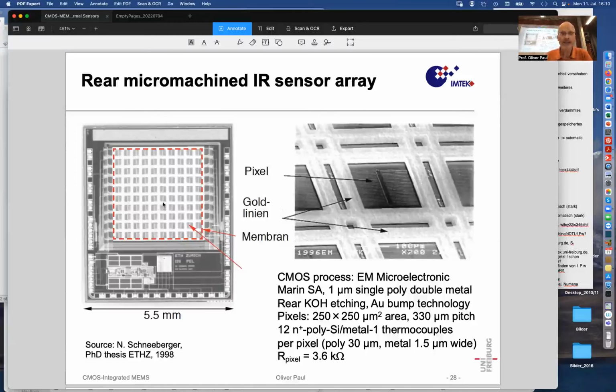And as we have also seen in chapter 2, those thin films are stressed. And so to have a large membrane of pre-stressed materials that would like maybe to expand because they are compressively pre-stressed could cause fracture. And so in order to prevent that, this whole membrane was stabilized by these white lines. You see these white lines? These white lines are actually double lines of pretty thick gold. So 25 micron thick gold, maybe here, I would say 100 micrometer wide.